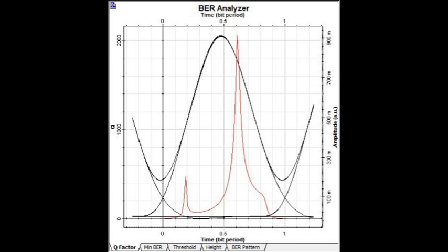The attenuation value plays a big role that can change the result value. Compared to the previous attenuation, with attenuation at 500 dB per kilometer, the Q factor at range 1 meter increases but decreases when the range changes to 5 meter. The value of eye height has a similar condition as before, which is decrease.